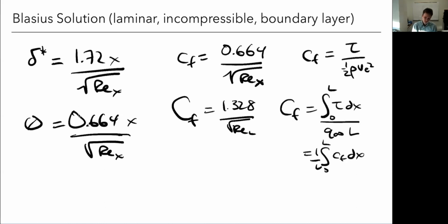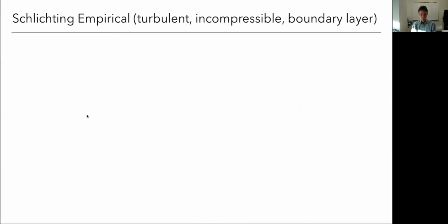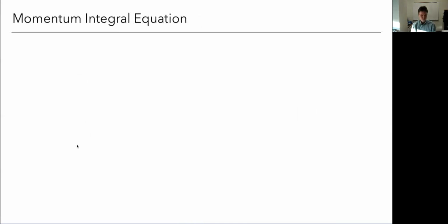For the turbulent case, there's not an analytic solution. There are empirical formulas. There is not just one, because empirical, there are many such formulas. The book shows one such formula you can take a look at. You'll note that these things grow faster, right? The displacement thickness, momentum thickness, and the boundary layer height grow faster, as we would expect. But I won't copy those down right here.